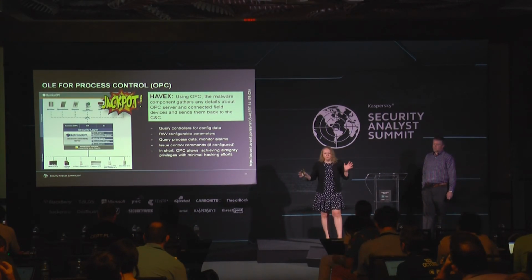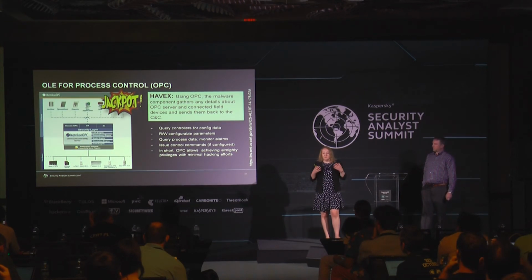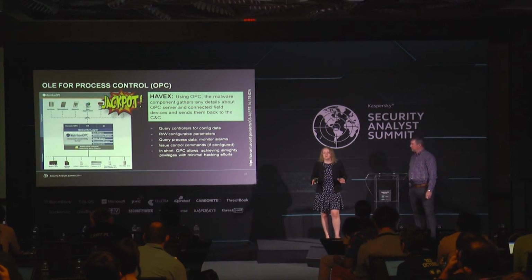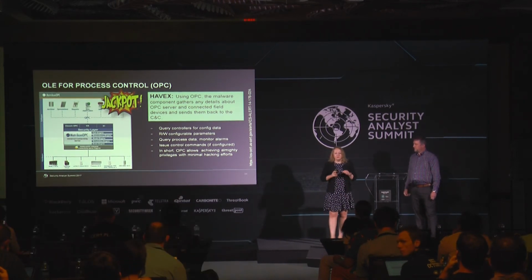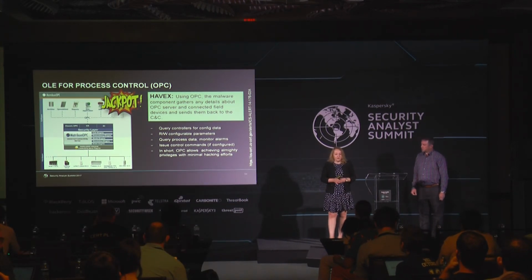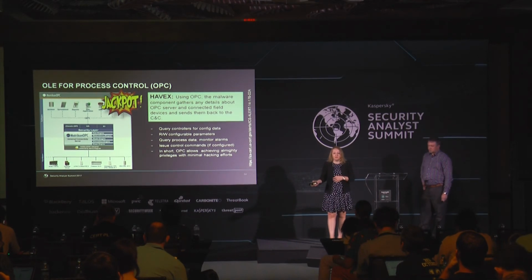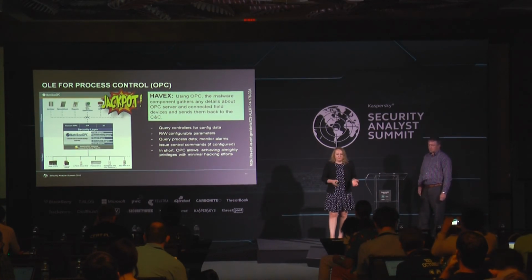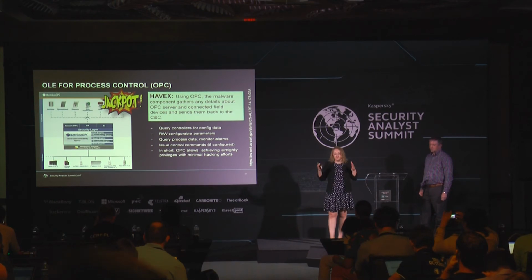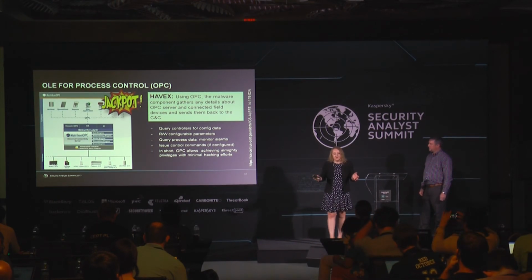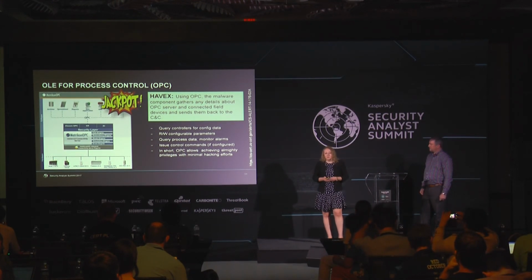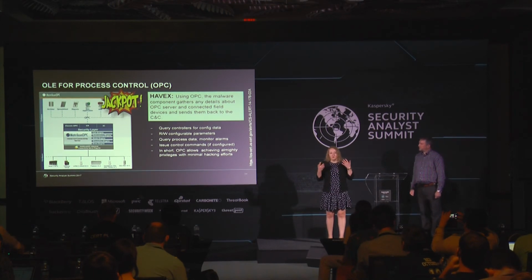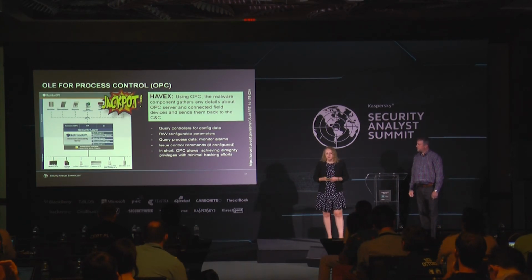For example, to overcome all of that madness of multi-vendor, if there is an OPC in the system, you want a jackpot, because that is a super powerful protocol which gives you super rights. You can write into the controls, change things, query process data, monitor alarms. You basically get one point where you can achieve all the tasks. It is a relatively weakly protected protocol, and it is an open protocol, so it's easy to develop exploits for it. So they need to be protected.